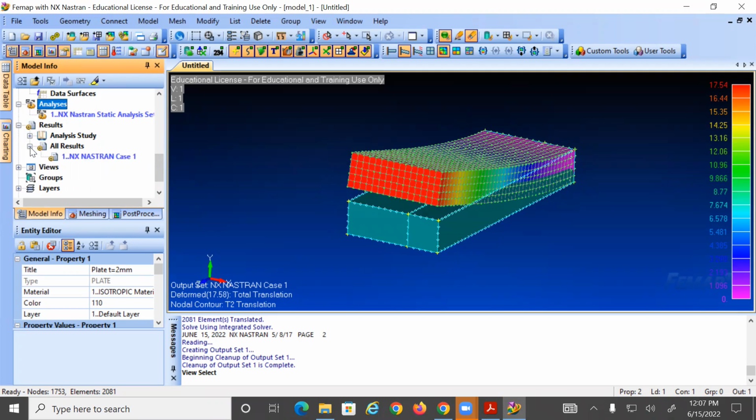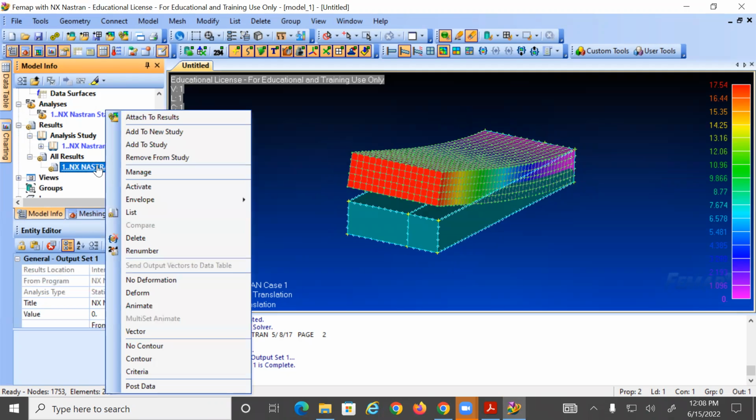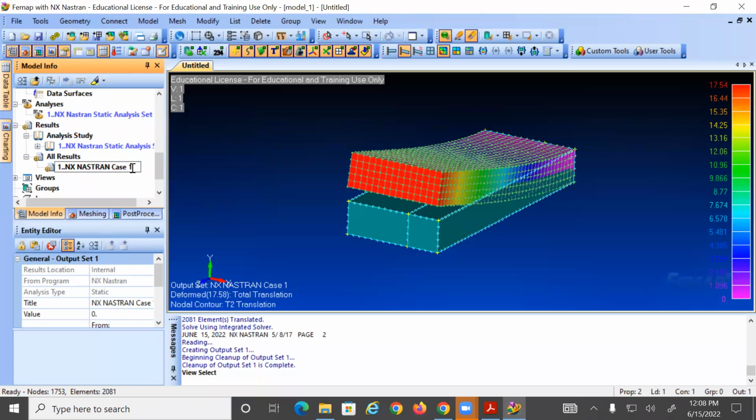This is, if you want, more realistic than the one we did the calculations for. So let's call this one case 1 for T equals 2 millimeters. Because in our assumptions, when we did the calculation, what was the assumption? That the panels were not effective in resisting bending, correct? Okay, so basically we say the outer panels are not resisting any bending. So here you see, this was for 2 millimeters.